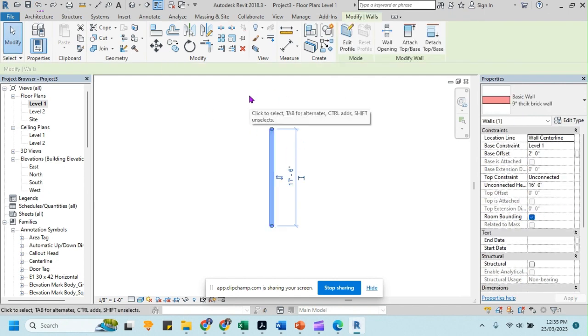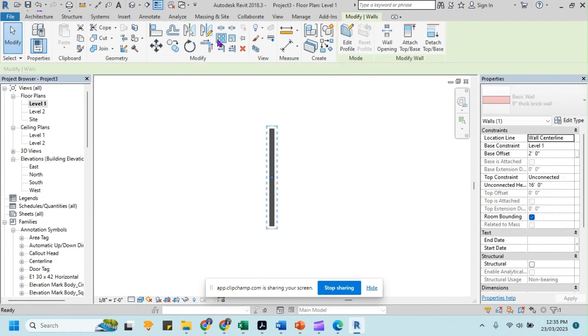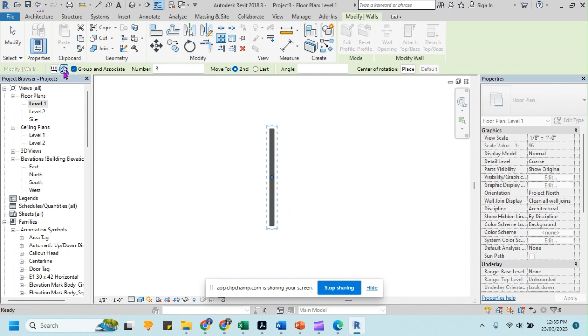Okay. We do this activity again. Go to Array, select the radial one, and this time I choose the other option, the last one. I pick the last one, which means I can change the numbers. I change the centroid, the center of rotation, and pick the last one. From here I begin, the first point is here.